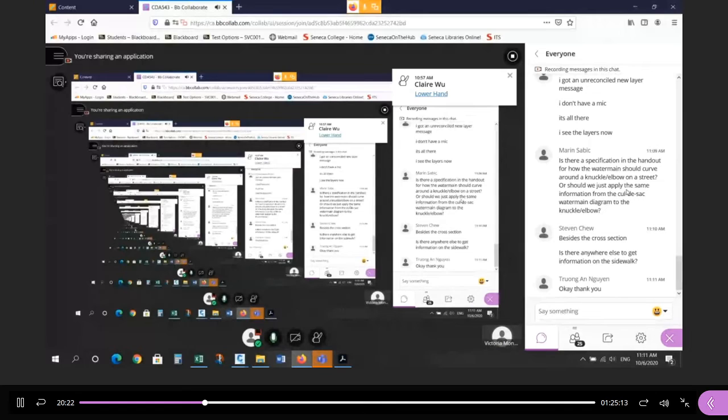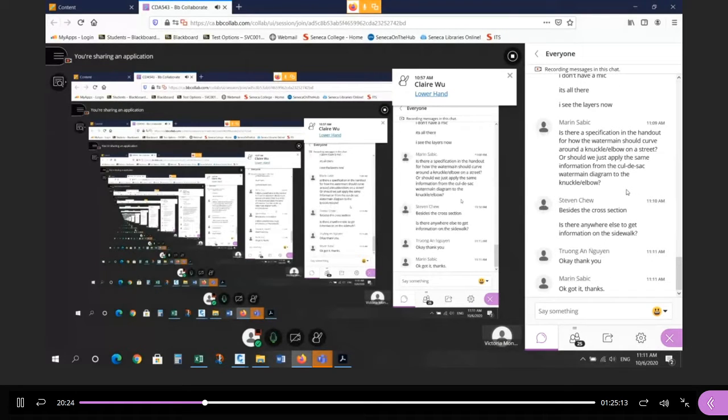Okay, and then you need to draw the loop in the cul-de-sac correctly based on the standard I gave you, a W7A, I believe. And then at the intersection, just extend it to the existing water main, and that's it. So just draw the center line of the pipe. You don't have to label any of the bends or the T's or the hydrants. Don't leave anything out except the line. If you want a label for the size, you can. We're going to use a 150, but we'll deal with that kind of stuff next semester. It really is an AutoCAD exercise, not a civil exercise.